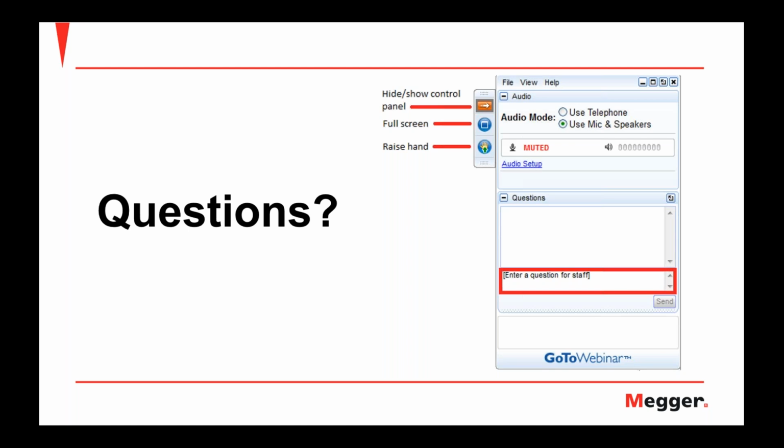Okay. What is float mode and boost mode? Can you please explain? Float mode is when the battery is fully charged. When the battery starts charging, it's going to draw a lot of current. And then as it gets fully charged, it'll draw less current. And then finally, it will go into what's called the float mode. This is basically where the battery is fully charged and there's just a float voltage. It'll typically be on a 2-volt cell, about 2.2 volts, right in that area. And it keeps the battery topped off.